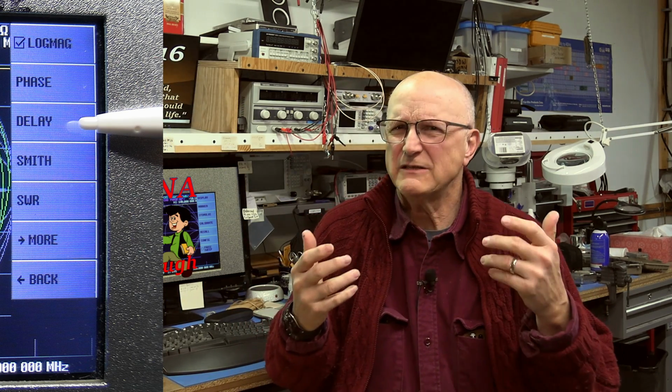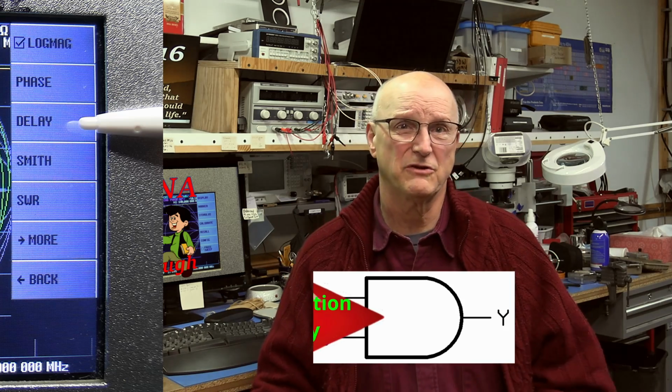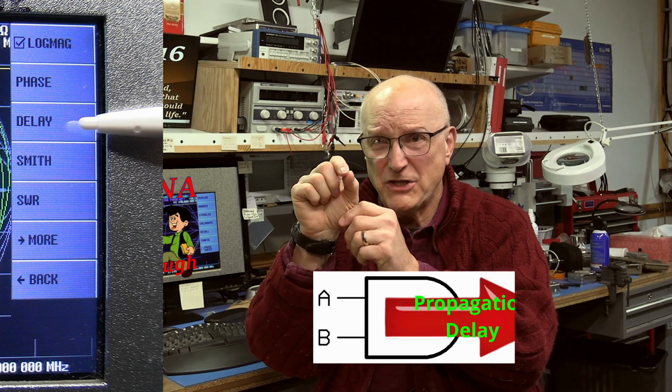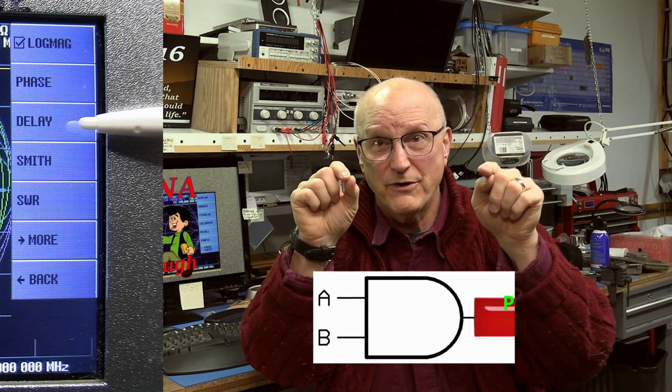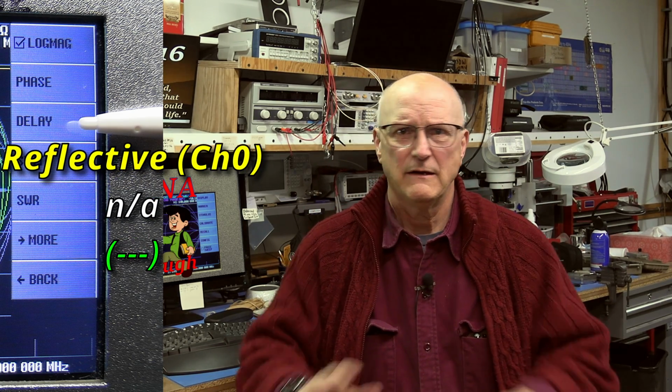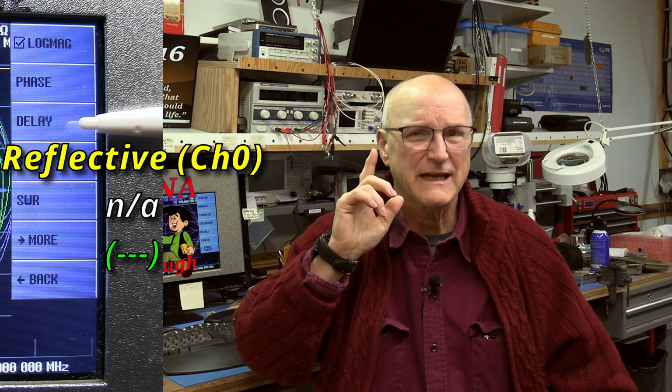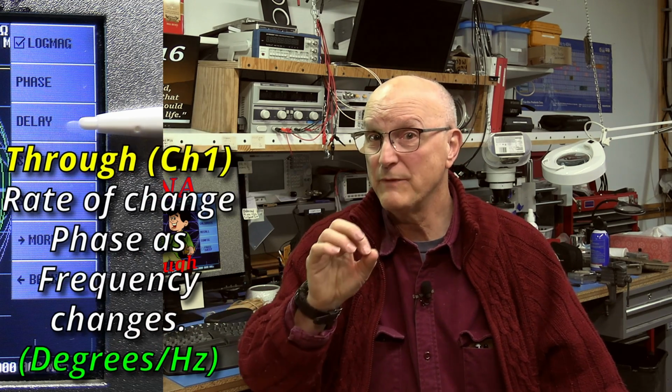Well, the next option on this menu is delay. Well, what is this whole delay business? Now, we're used to thinking about things like the propagation delay through a digital logic gate. In other words, the time it takes for an input logic change to be seen at the output of a gate. But now we're in the frequency domain of the VNA. Right out of the gate, it doesn't have a lot of meaning in the reflective realm. However, it has a lot of meaning in the through measurements.